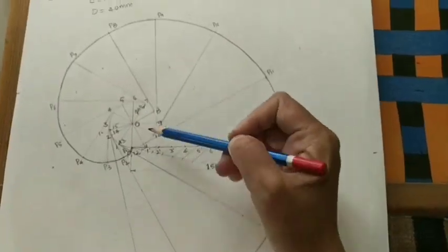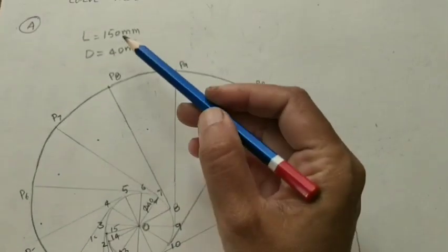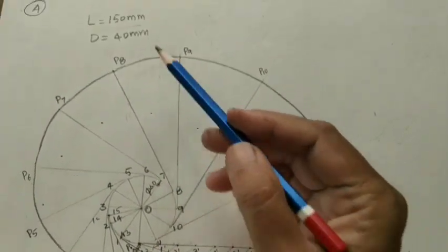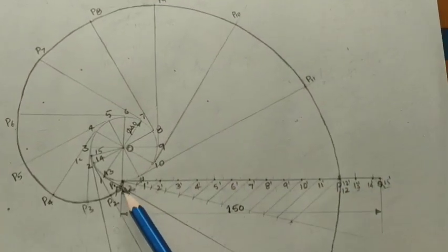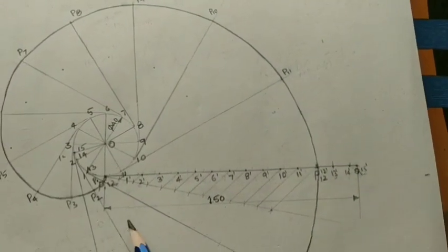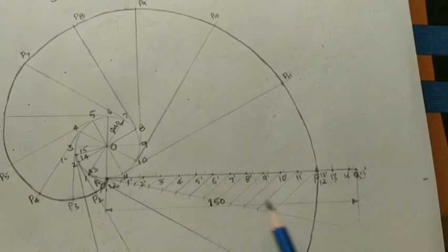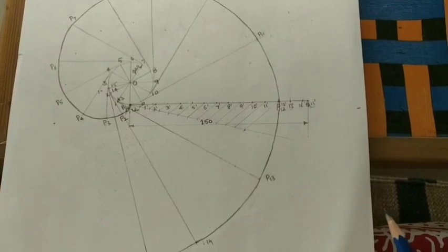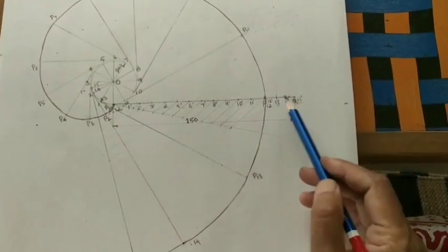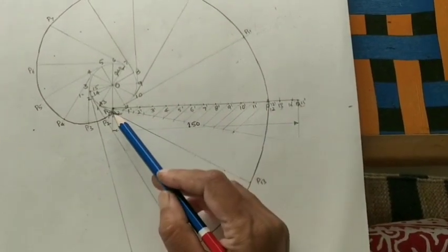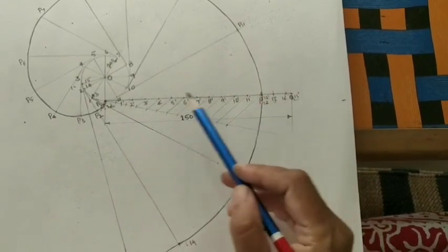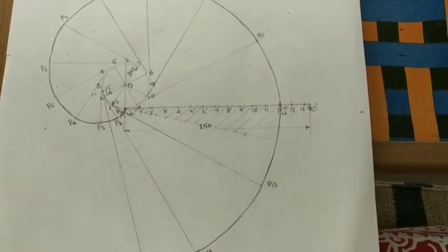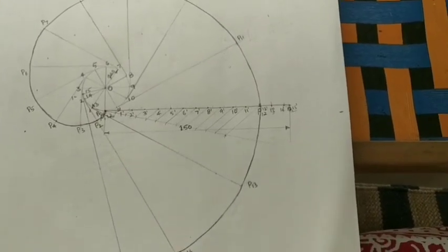Okay, so here mark the given dimension. Diameter is how much? 40 mm. Take any one of the diameter, keep diameter symbol 40, and then PQ length. Thread length is P. Here do the extension lines, and do the dimension line at the middle, write down 150 mm. This is a method of doing an involute if this rope length is more than the circumference length. Circumference length is only this one, but they have given more than that length. This part is coming here. So this is the method of doing an involute.